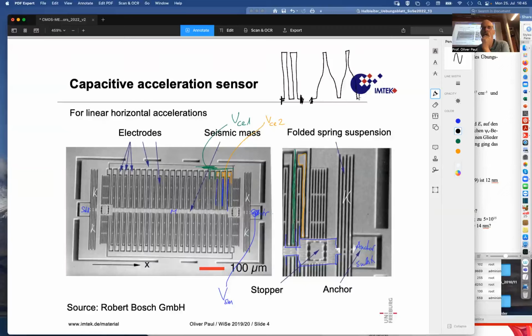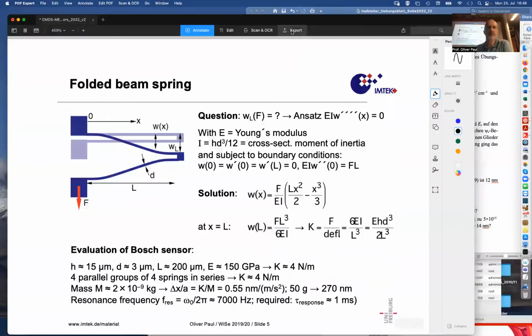Now you see that there has been, from the original distance, the equilibrium distance, let's call this D0, there has now been D0 plus some significant delta D. And this expansion of this structure is analyzed on this page. You see only one of those zigzags being pulled apart by a force. And that pulling causes this beam material to bend and then to bend back.